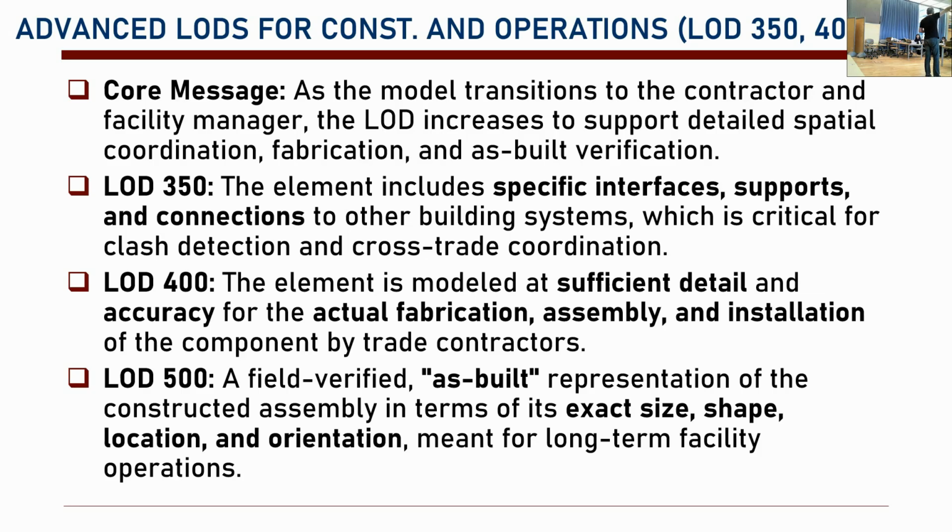Which maker? Which model? Okay? Who did that? When was it manufactured? Who purchased it? Okay. What kind of maintenance data do we have? All these are put in LOD 500. Okay. As-built representation of the construction assembly in terms of exact size, shape, location, orientation, meant for long-term facility operations.